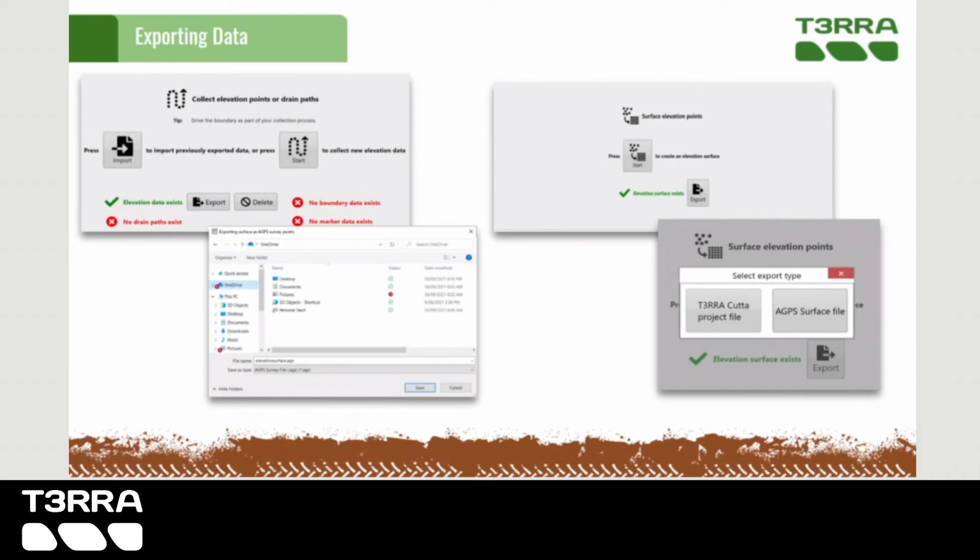When exporting raw data points from Terra, field and drain survey data will be exported as a CSV file. Boundary survey data will be exported as a KML file. Clicking on the Export tab in the Collection homepage will open the File Explorer tab. There you can select a folder or USB to export the data to.